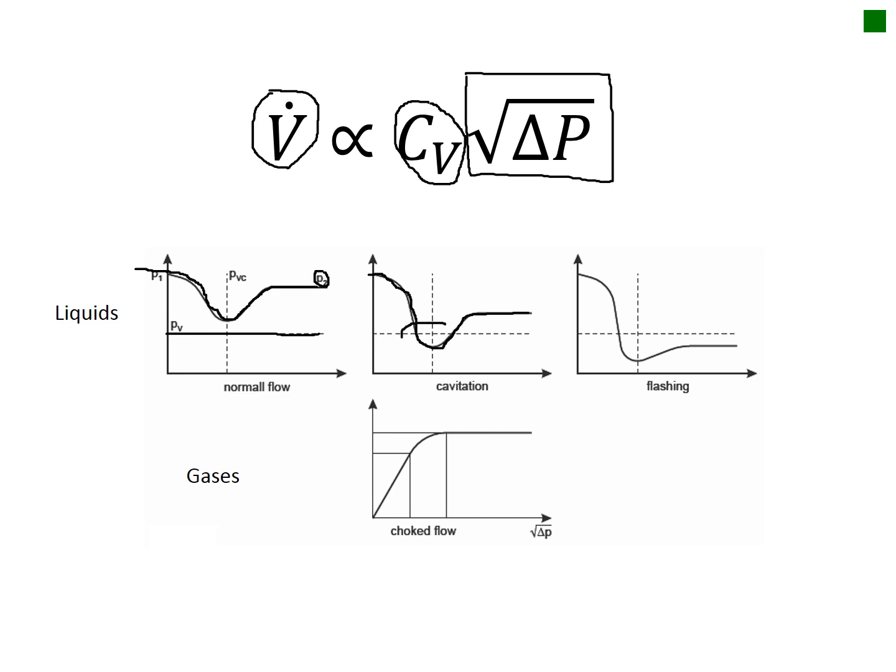In this region, since we're below the boiling point of the liquid, it actually flashes into a vapor, and then when the pressure rises back up, it collapses back into a liquid, and we call that cavitation.